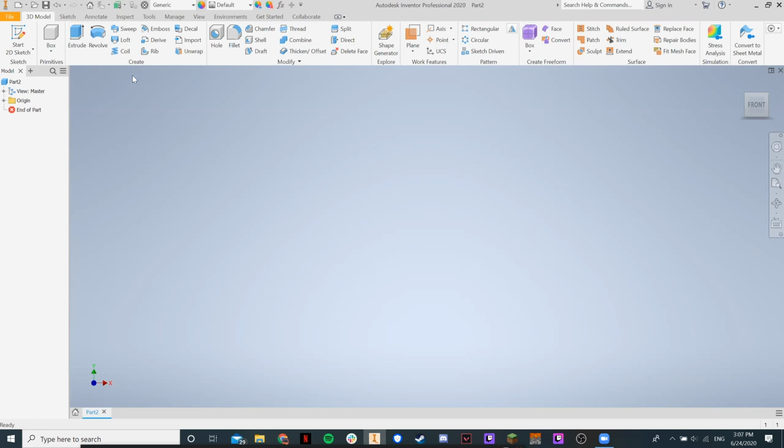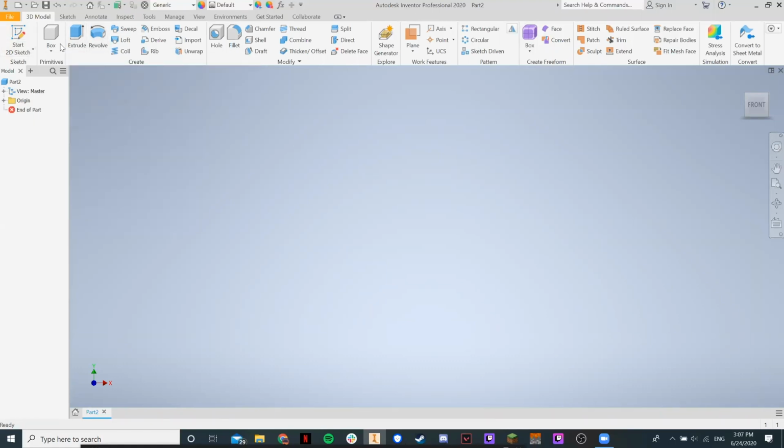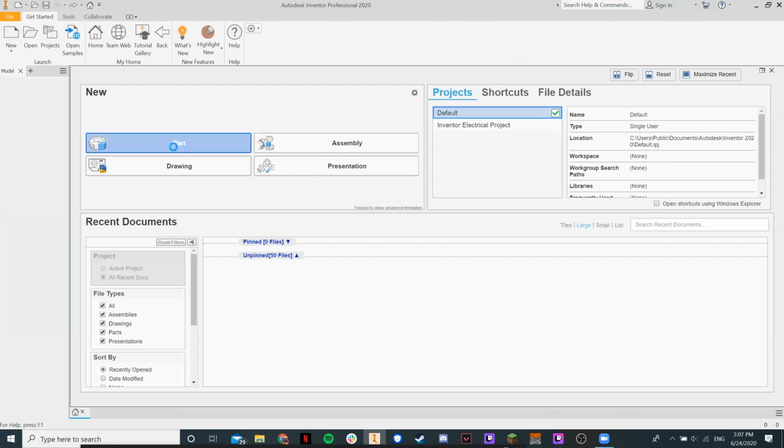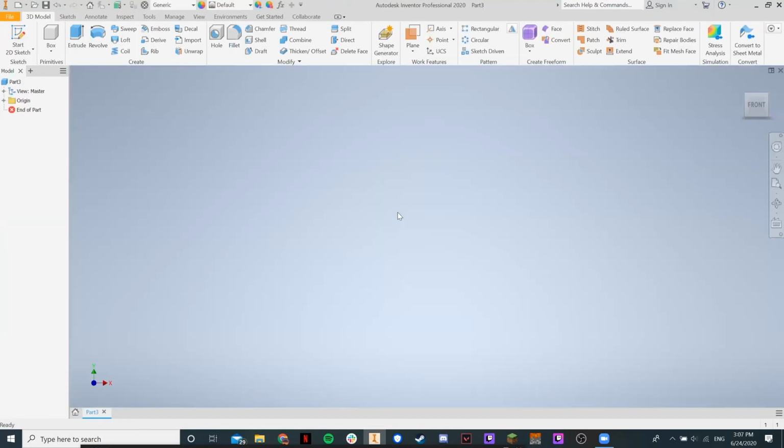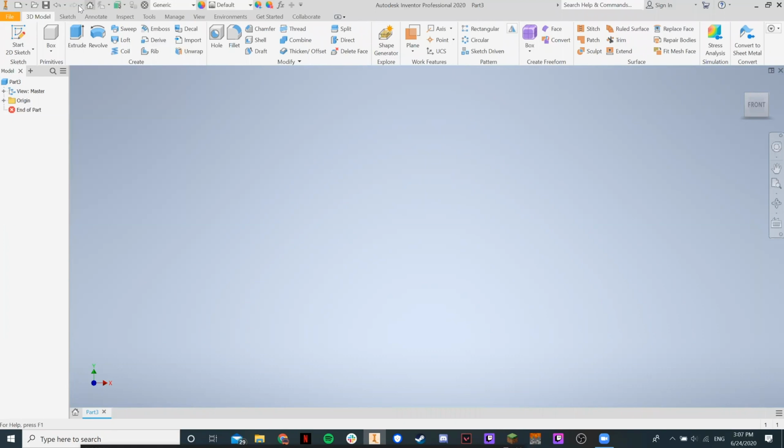So today we're gonna learn about the other important 3D modeling tool. Besides extrude, we're going to learn about Revolve. So Revolve, it's pretty self-explanatory, the name. It basically just revolves a 2D sketch. So let's make a cone with the revolve function, yeah?